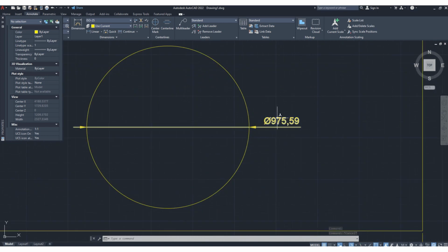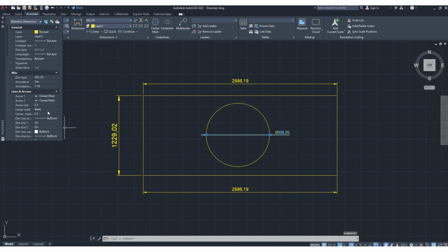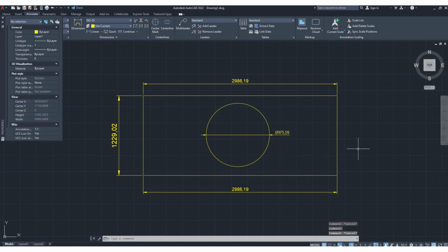If you want to change further in a bigger size, the only thing you need to do is change this scale. But as you can see, the entire drawing scale is 1:1 only. No need to change here. Also, this is for the dimensions individually, or you can select all the dimensions at once and select a single scale, if you want all the dimensions to be in the same size. But if you want different sizes, then individually you need to change the scales for each dimension.